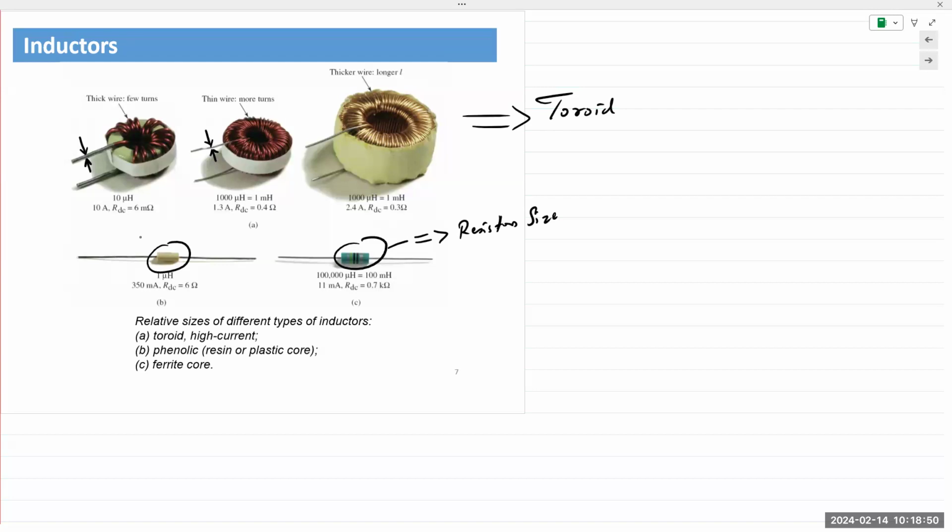Okay, which is also the operating principle behind an electric fuse. You have a fuse physically constructed with a thin wire. If the current passing through that wire increases beyond the capability of its construction, then we say the fuse blows. What exactly happens is the current flowing through there causes so much heat that it just breaks the connection. And so thicker wire, large current carrying capacity; thinner wire, low current carrying capacity.